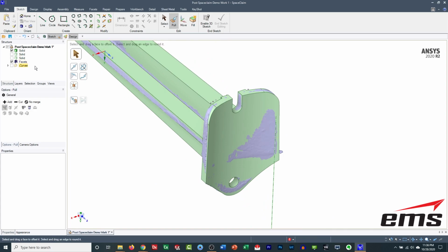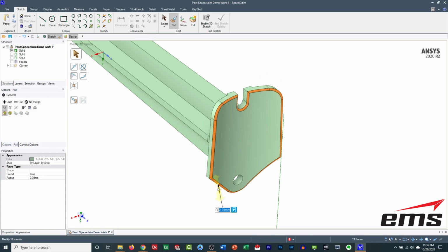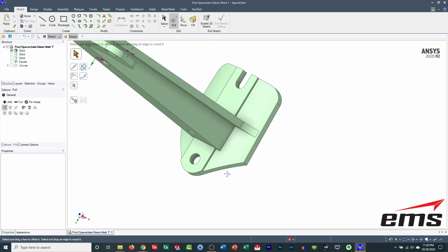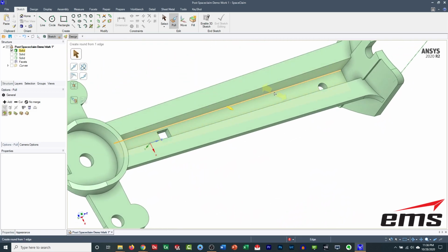Let's go to the back here for a minute. So let's say we do want to add some of the smaller radii. We can double click on it to try to get a chain all the way around, and then push in and key in an amount if we want. So adding fillets is easy. I think down in here there's some major fillets.